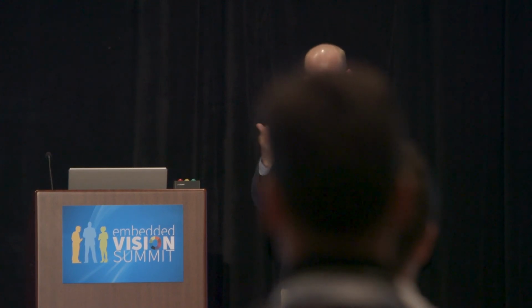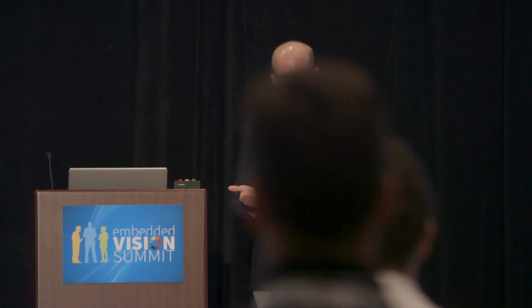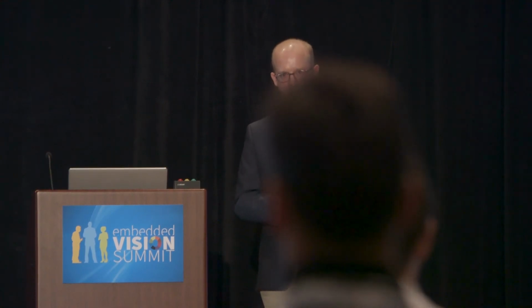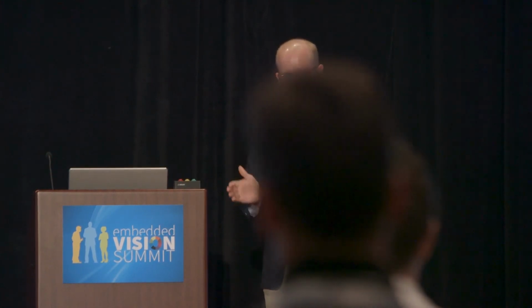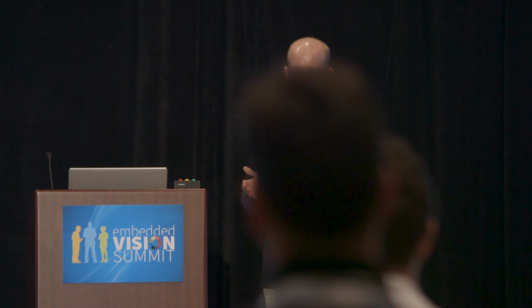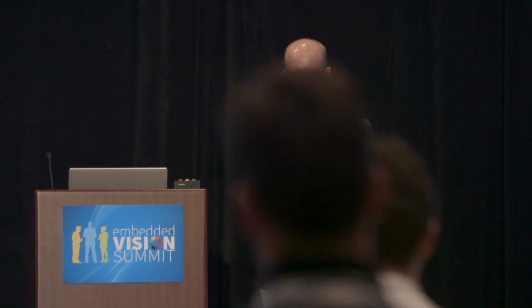With 3D lasers, you have the scan time that you have to compensate for. So you have to have very accurate understanding of system motion through the environment to back out, I'm moving at 90 degrees per second horizontally, and I'm taking a 20 millisecond scan, and that actually introduces a fair amount of angular shift over the course of those 20 milliseconds.